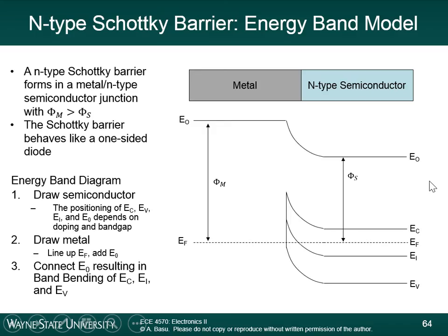there's a discontinuity here. The difference between the metal-semiconductor junction and a PN junction is that in a PN junction, the connection looked more like this, right? But in a metal-semiconductor junction, you only have half of this, so it looks like just half of an arc. In a PN junction, this arc would continue on to the EC on the P side of the semiconductor.